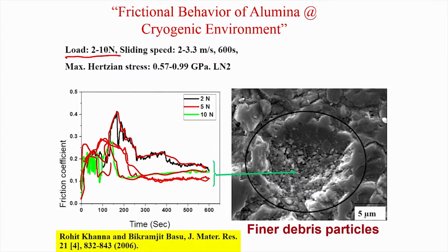It goes through very high values, up to 0.3, 0.4, within the first 3 minutes, and in the next 7 minutes the friction drops and the frictional coefficient goes to around 0.15, somewhere in the window of 0.1 to 0.2. That is how the COF changes.